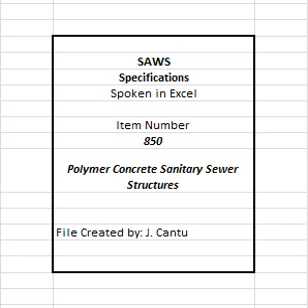A. Hydrostatic testing shall be conducted by utilizing approved plugs to seal all influent and effluent pipes in the structure and filling the structure to the top of the cone with water. 1. Additional water may be added over a 24-hour period to compensate for absorption and evaporation losses. 2. At the conclusion of the 24-hour saturation period, the structure shall be filled to the top and observed. 3. Any measurable loss within a 30-minute period shall be considered an unsuccessful test and thus require the contractor to assess the needed repairs, perform such repairs, subject to the approval of the engineer, and notify the inspector when the retest will be performed.